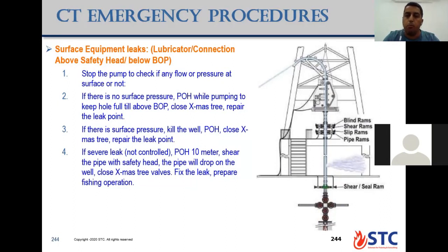If you are on bottom, so you have space inside the well from the bottom, you will shear the pipe with the shear seal or the safety head. The last option we use is to cut the pipe. The pipe then will drop down inside the well, so it will be far away from the Christmas tree valves, so you can close the Christmas tree valves safely, fix the leak point, and prepare for the next operation, which is a fishing operation. So you will find the steps here, start by trying to deal with the problem.